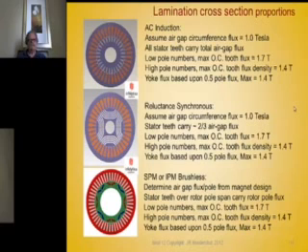For the yoke, the flux density in all these machines is based upon 50% of the pole flux, because the pole flux splits when it goes through a set of teeth. Half of it goes clockwise around the stator, and the other half goes counterclockwise. It's not going to go around one side and not the other.